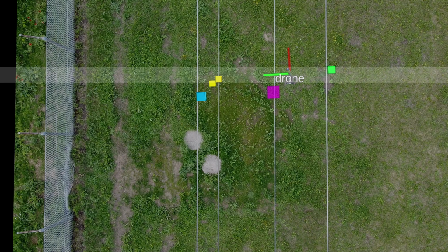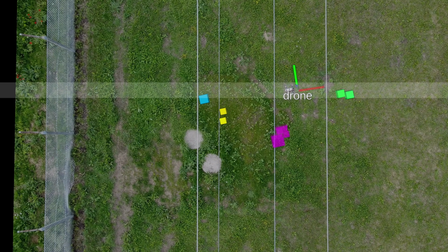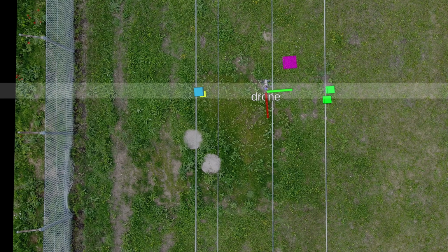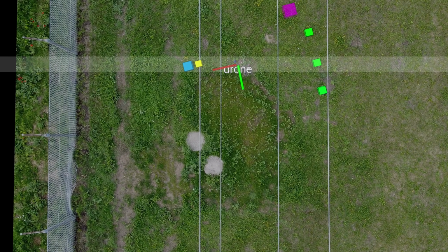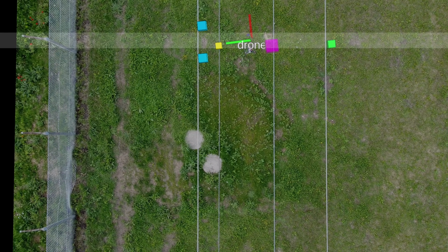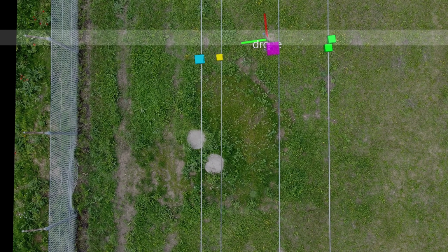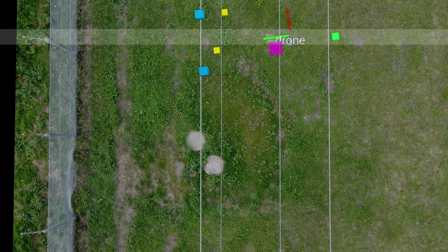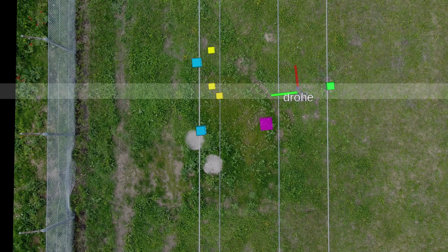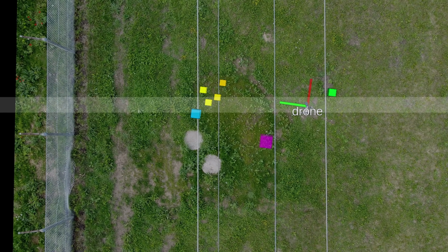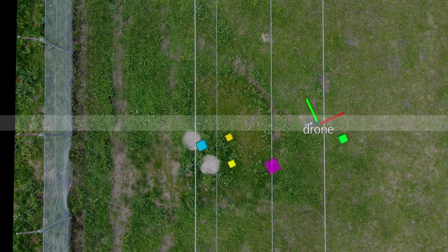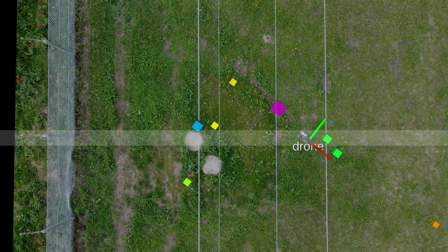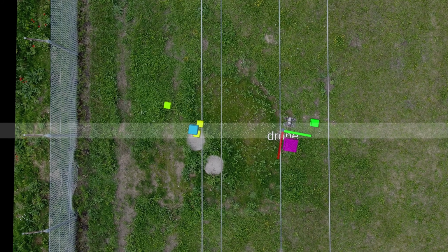While developing the system, an interesting phenomenon was observed. The radar sensors typically detect the power line at its closest point to the sensor. In this clip, that would correspond to approximately the white horizontal bar. As the UAV yaws around, most detections from its surrounding sensors approximately correspond to the closest point on the power line. This phenomenon can be utilized to simplify the power line avoidance scheme.